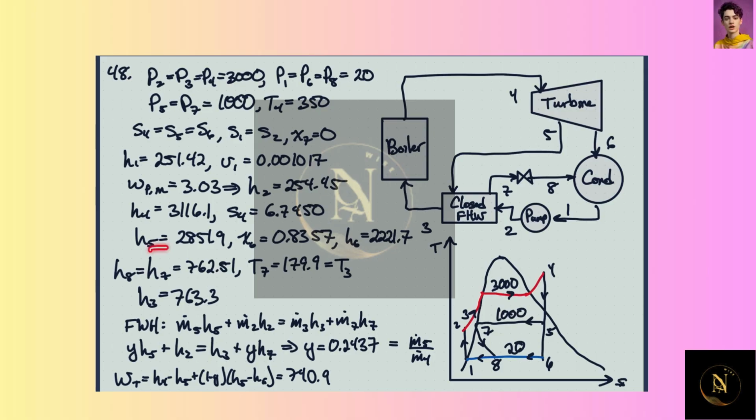At 5, we can get the enthalpy because we have the pressure and the entropy now. It's the same as here. So this equals S5 and equals S6. And then we have at 6 then, and it looks like I drew this a little wrong because this should be outside. I think this is a superheated value. So this should actually come in like this. Anyway, so this should be not in the two-phase region.